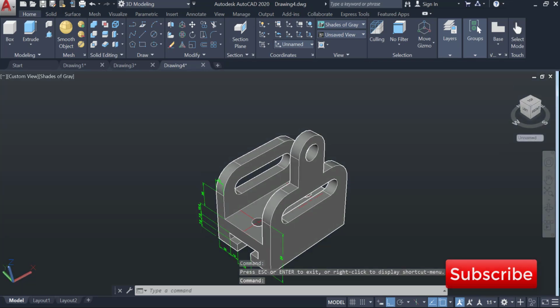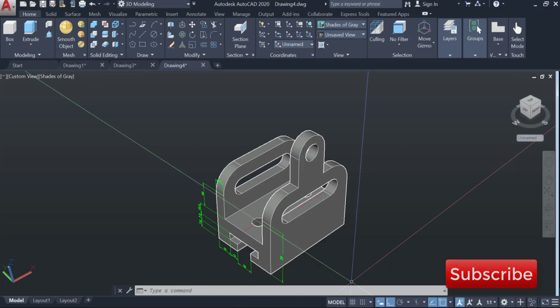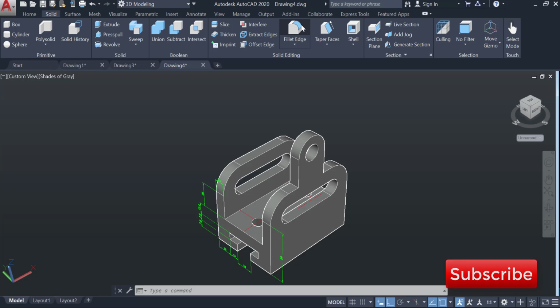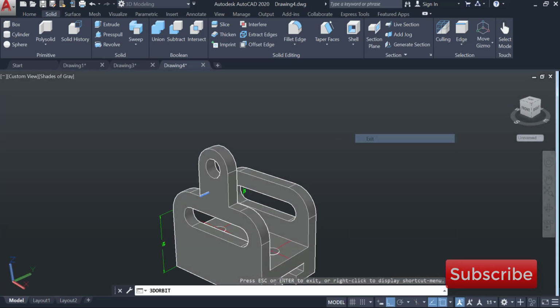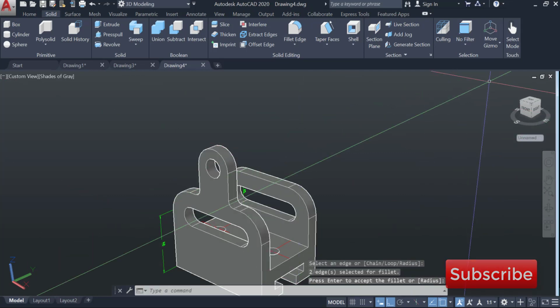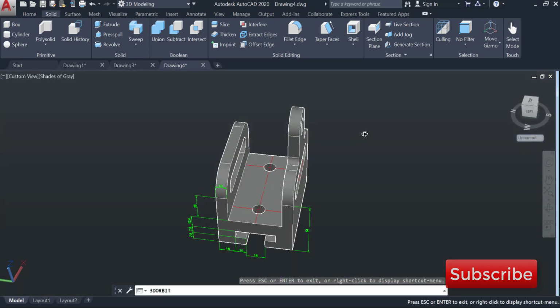I think there's some fillet here. Okay, yes, there's fillet here, and he made it 5 diameter. So let's make the fillet. Go to solid, make it fillet. We need to select fillet here, and also we need to make a fillet over there. Okay, over here. So let's select it and make it radius of 5. Enter. So now this is truly done. Yeah, truly done, my friend, truly done.